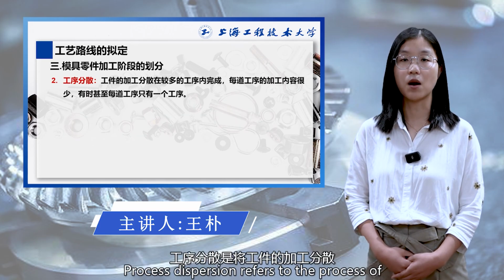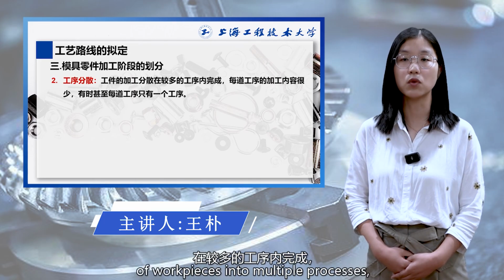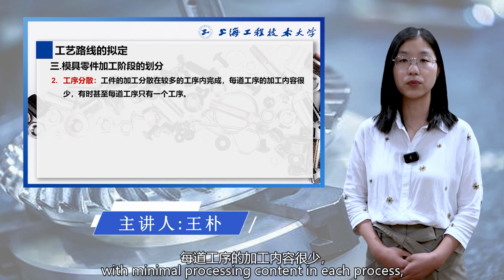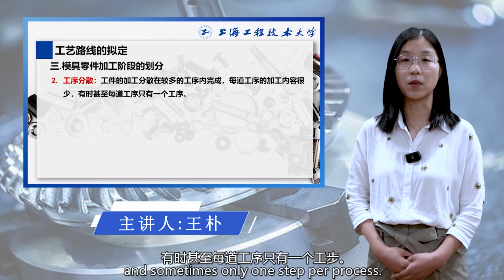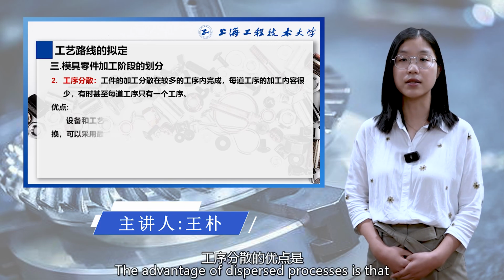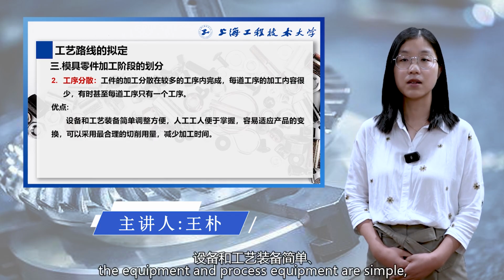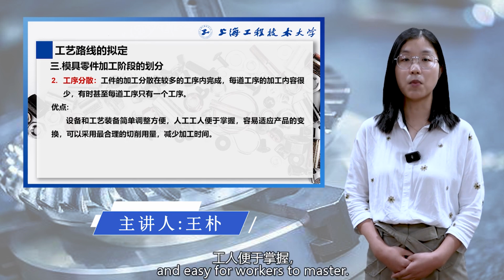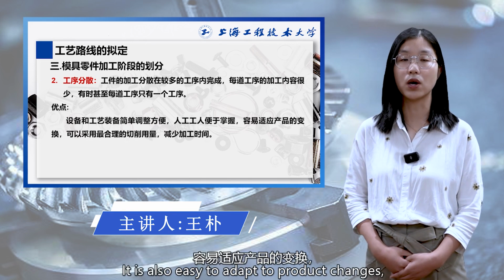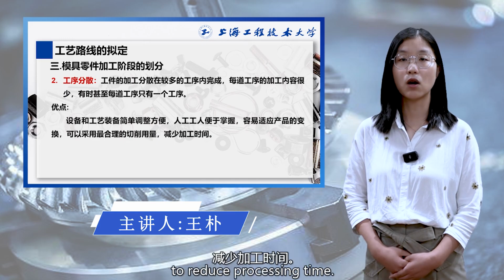Process dispersion refers to the process of dispersing the processing of workpieces into multiple processes with minimal processing content in each process, and sometimes only one step per process. The advantage of the dispersed process is that the equipment and process equipment are simple, easy to adjust, and easy for workers to master. It is also easy to adapt to product changes, and the most reasonable cutting parameters can be used to reduce processing time.